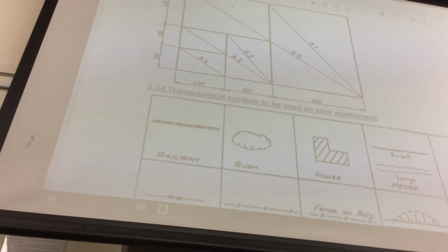And so that's something to get your head around a little bit, because it's really important in a drawing to put whether it's an A1, A3, A2 on the bottom of the drawing. No use leaving that out. If you just put scale 1 to 100, and the client hasn't got AutoCAD, asks for a copy, you print it out to him, you might just give it to him on an A3 sheet, and he's putting the wrong scale rule on it because there's no reference to whether it's A1 or A3 or A2 or A4 or whatever. Very important to put that on. Don't leave it off.